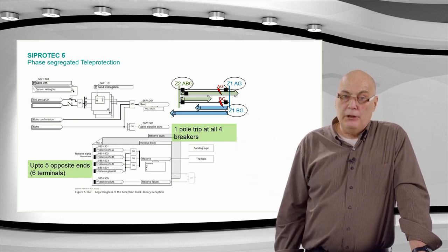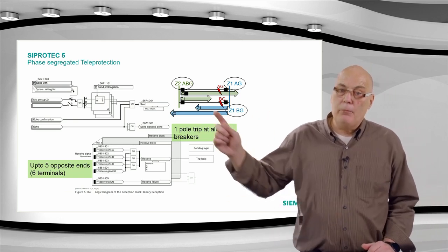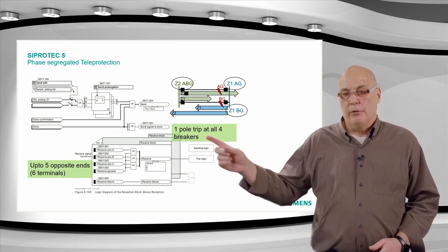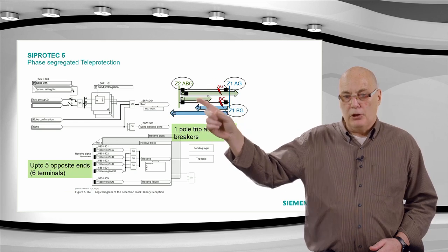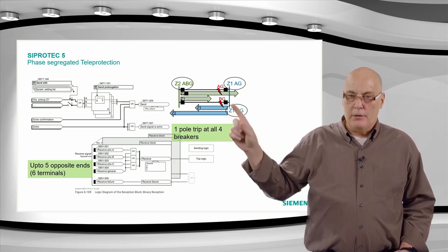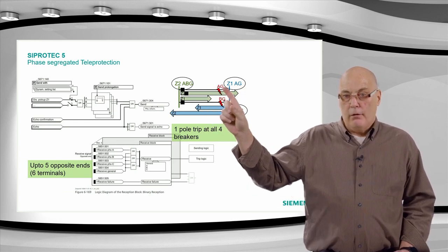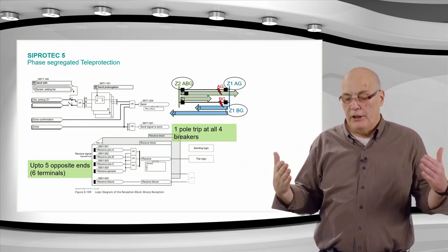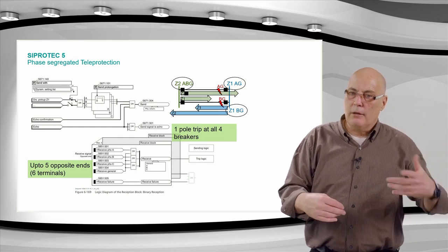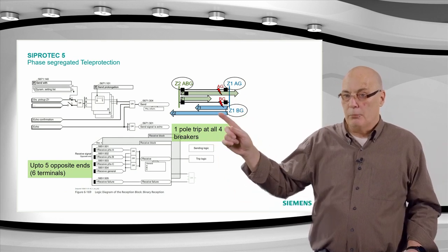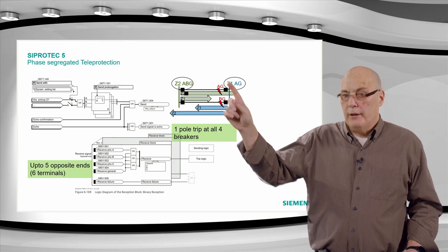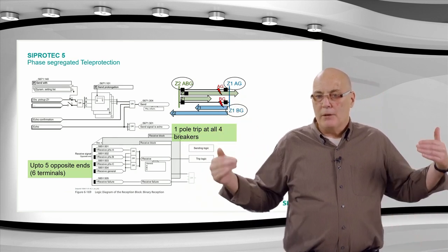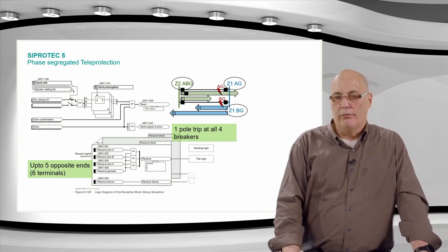So the teleprotection is extremely important here, and the other thing that can happen on these double circuit or multi-circuit lines, you get inter-system faults. For this example we've shown it's the same voltage potential, maybe they were actually coupled on both sides as well, and you get a fault, A ground on the one tower and B ground on the other tower. It's probably an inter-system fault where they are flashing over to the tower, and the arc on the tower burns into the other line. Normally, if these were 2 independent lines, not on the same tower, the chances of a fault A ground, B ground happening simultaneously is very, very small, very remote.